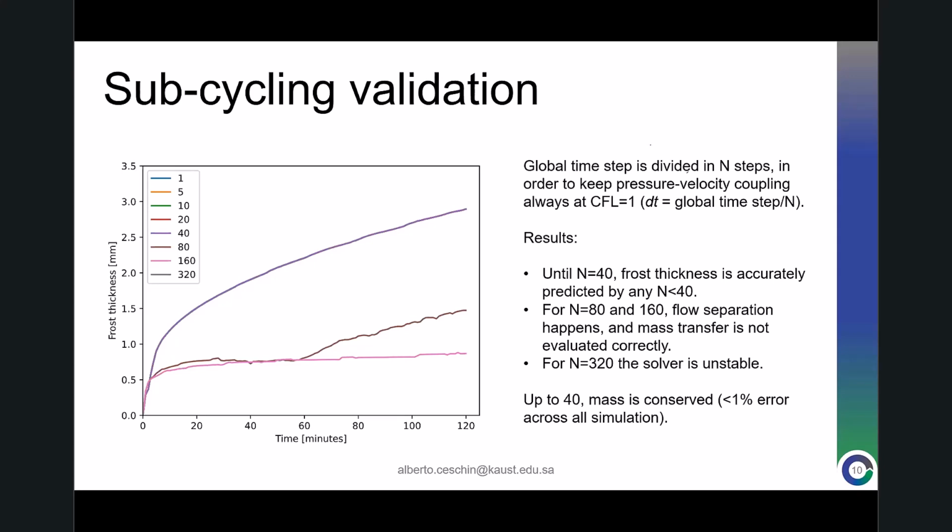But if we still increase the global time step, we have this weird behavior because we have separation, so we can't evaluate properly the mass transfer because we have recirculation inside, and the frost is not thickening much anymore.